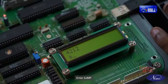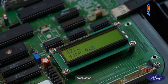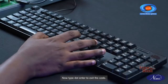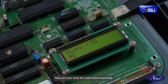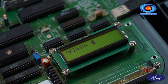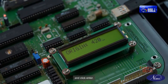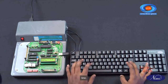Enter SJMP. Type the same address displayed on the screen and press enter. Now type .enter to exit the code. Now we must verify the code before executing. For that, click U and enter. Now on the screen it will display origin. Give the starting address of the code, that is 4200, and click enter. Check each line and click enter to check the next line.